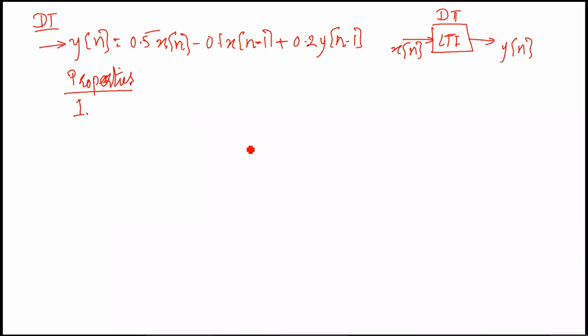Sir, this is a stable and causal system. Okay, you gave me two properties. You said it is a causal system. Very fine. First property, that this system is causal, and we know there is no n plus any term present. Second property you gave me was that it is a stable system. First property I agree. Second property, with experience I know it's a stable system, I just know it from the equation I have written.